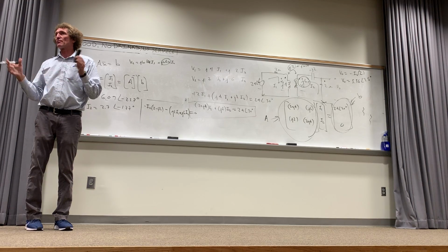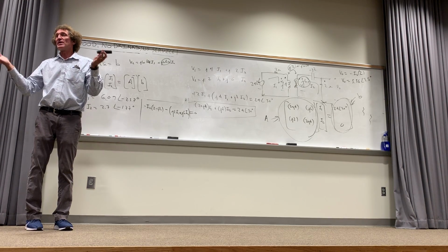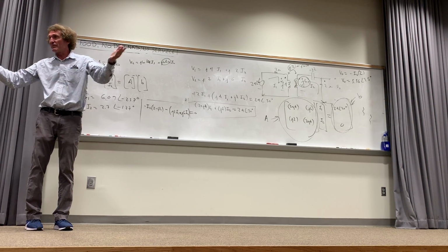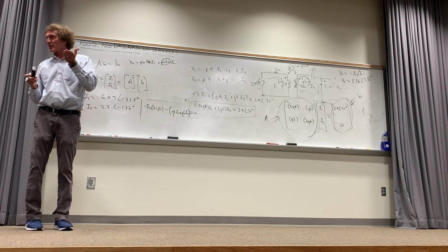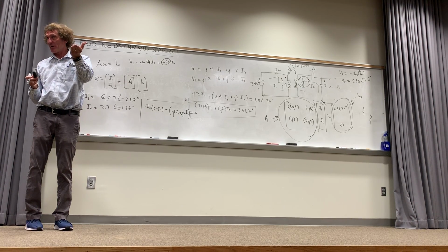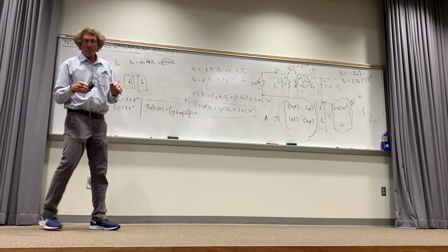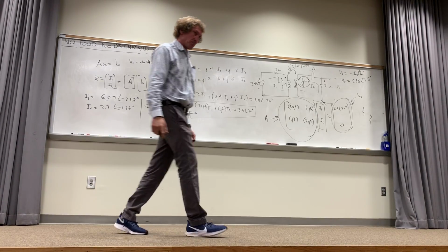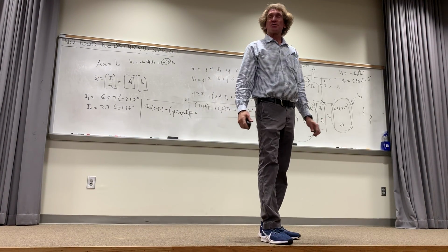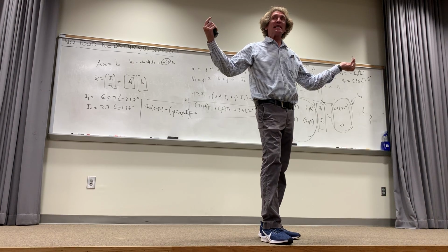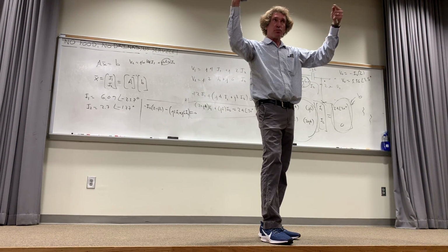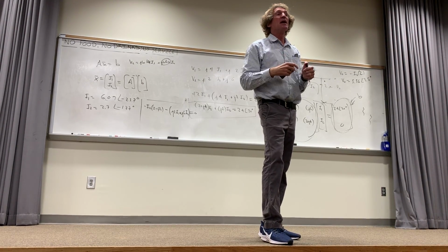That's something I'm trying to really underscore. That is given. If you look online, you're going to see that isn't given in a lot of stuff. In these problems, they'll give that. They're constant frequency. Is the currents coming into the dot a purely standardized thing? That's the standard way of doing it. You have currents entering the dots, voltage developed positive at the dot, negative at the opposite.